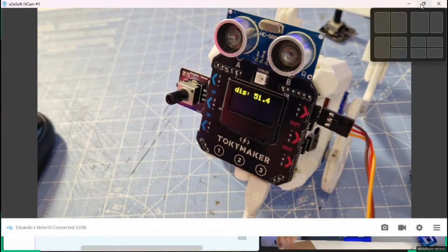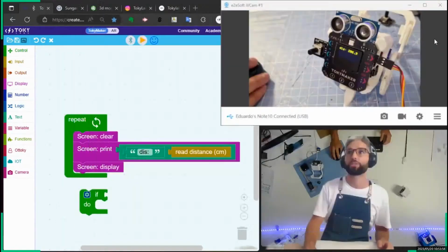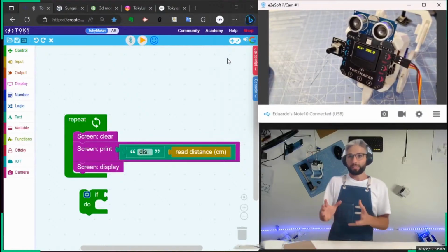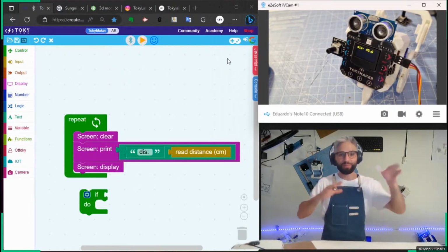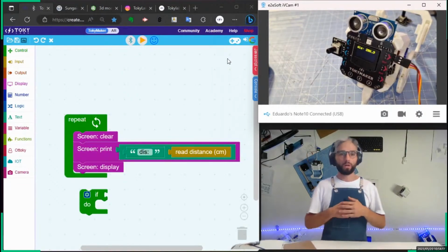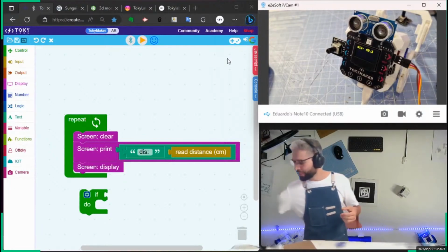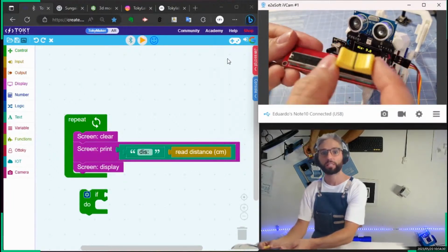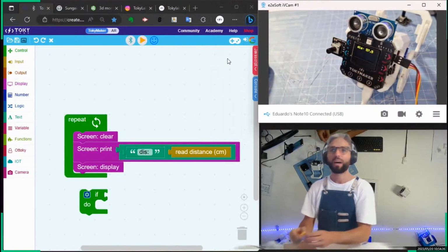There are many ways of detecting distance. This is maybe the most convenient way, but it has some limitations, of course. For example, if you want to measure the distance of something inside a tunnel or a cylinder, you can't use echo because the sound is going to be bouncing all inside the wall, so it's not going to work. Then you want to go to optics or other ways of measuring, like conductivity or even mechanical things, like this one, for example. You can use this as a distance sensor when the object is pushing, so you can know exactly the position. There are so many ways.